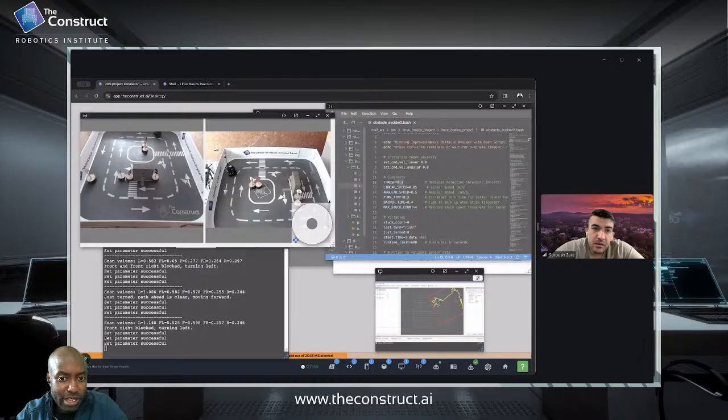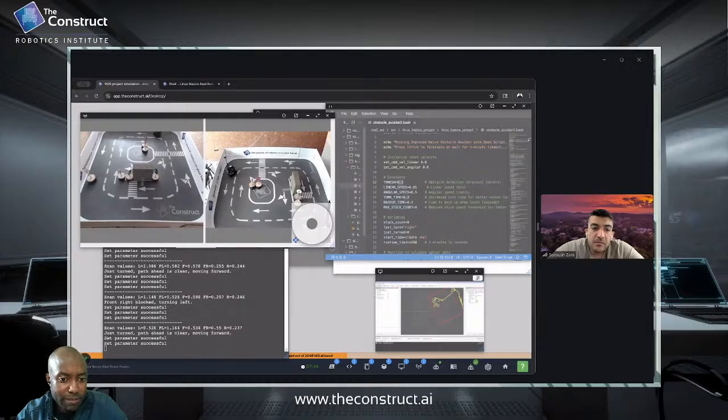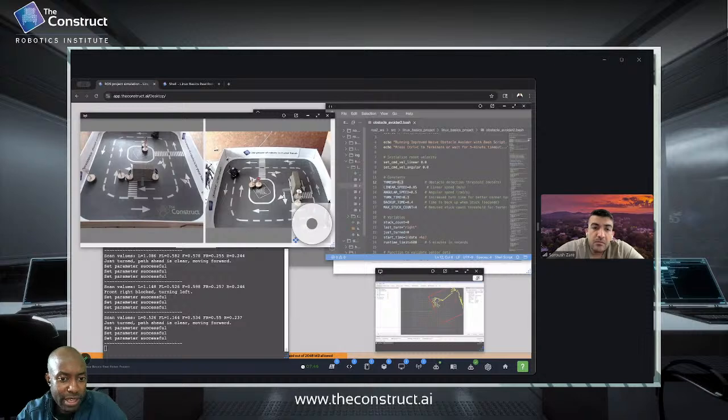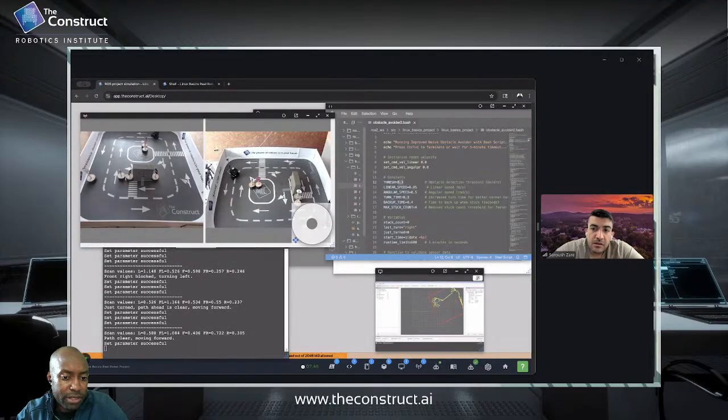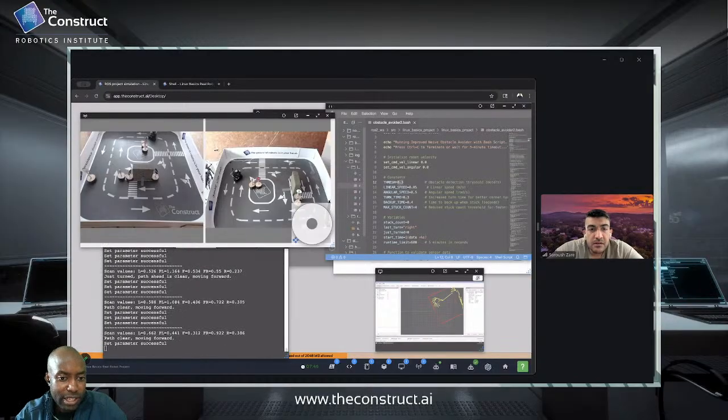So when it considers the front to be free and it's got this particular distance, for example, let's just say 2 or 1.5 meters, right? It's supposed to use the whole distance before reconsidering how far the obstacles are, because the assumption is the whole 1.5 meter distance is free of obstacles, so I have to go for that long. But right now we see it's constantly stopping and checking, right? Even if there are no obstacles in front of it. Yes.